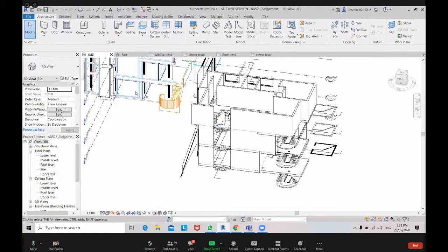So here, if you see in the floor plan, go and zoom a little bit first. You see the north should be here. Sorry, wait, should be like this. And Revit north, true north is here. So if you measure this angle, it is minus 45 actually. So I put here negative 45. Okay, see, automatically it has become 315, which is okay.